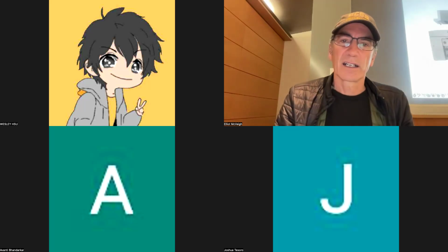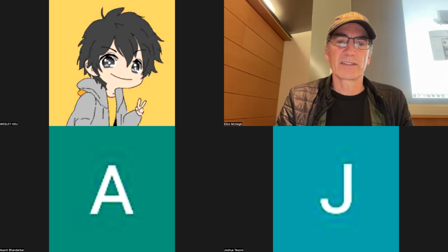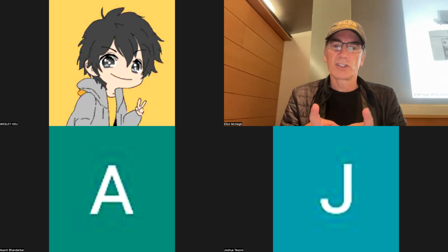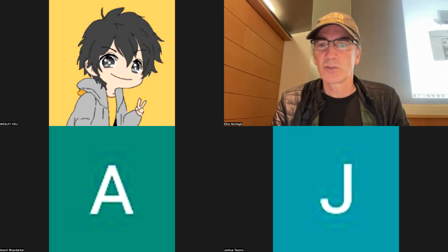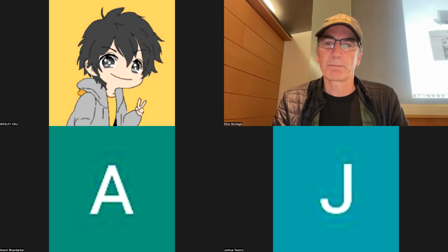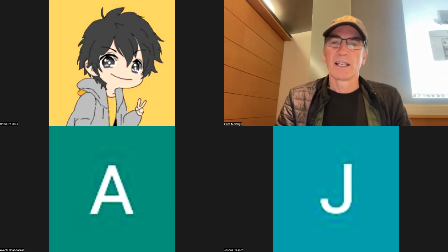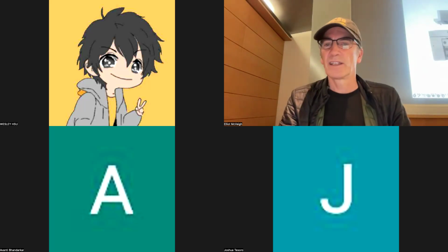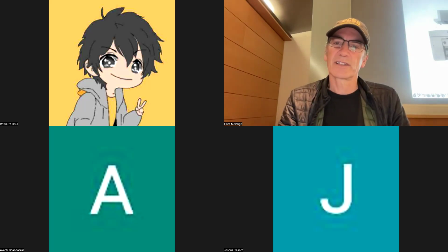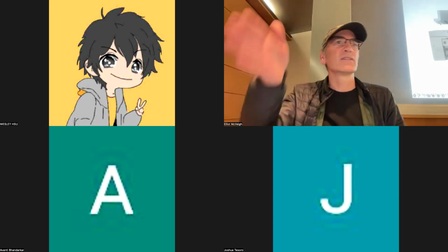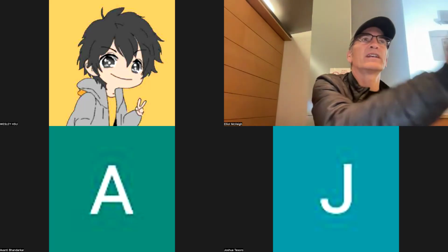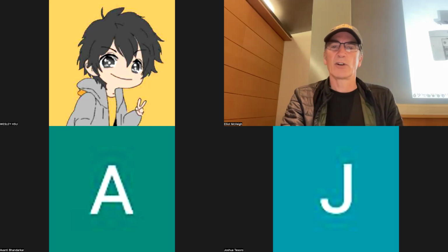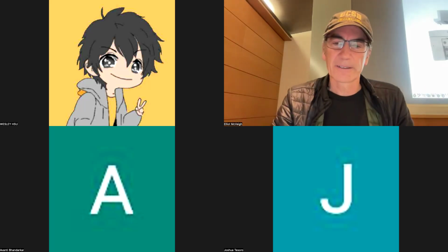Here's a classic detector, where we have these scintillators, and below the scintillator we have the photodiodes, and these are on chips. Basically, it's like a 32 by 16 chip or something that they all just plug in. And on this detector, this is one unit that's been pulled out. This is the Z direction. So you have essentially 256 independent slices being sampled simultaneously, because this is the Z direction. And then you would have a whole set of these things plugged in to make a detector.